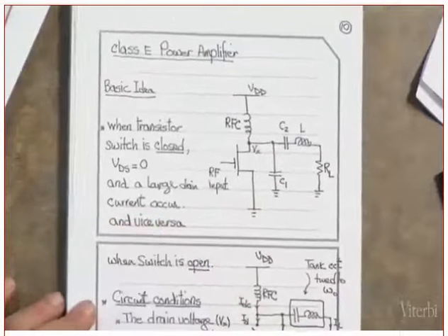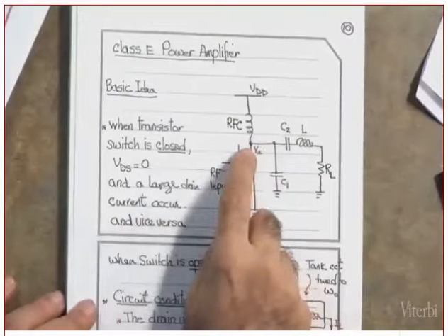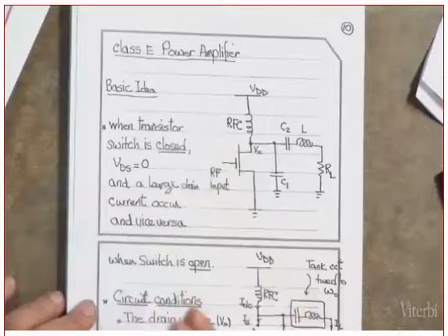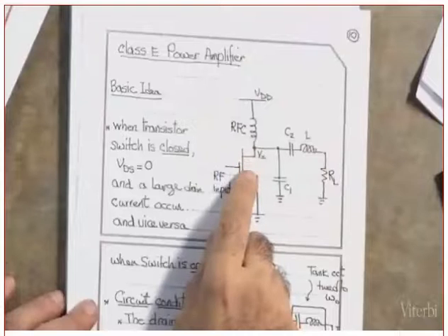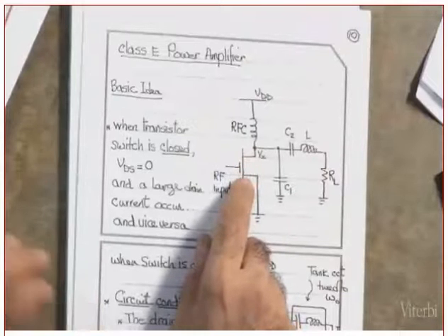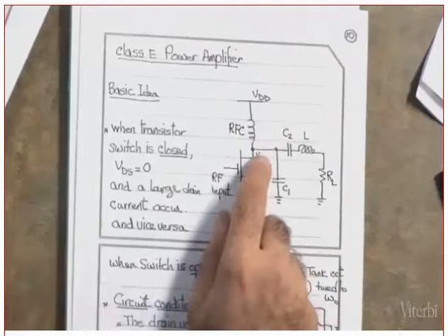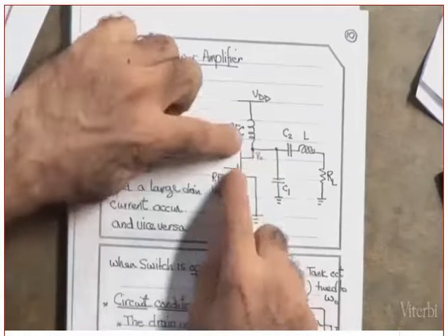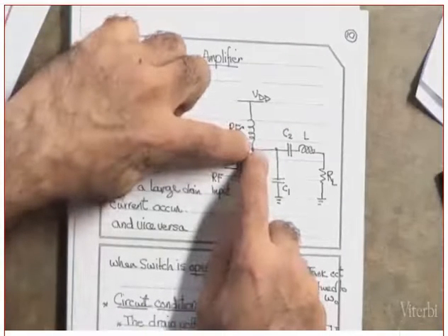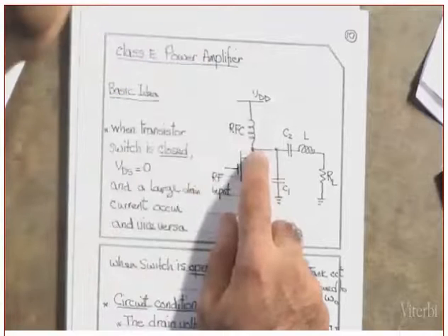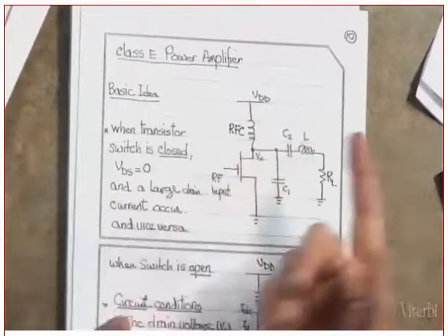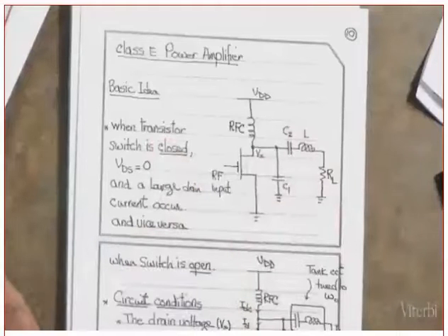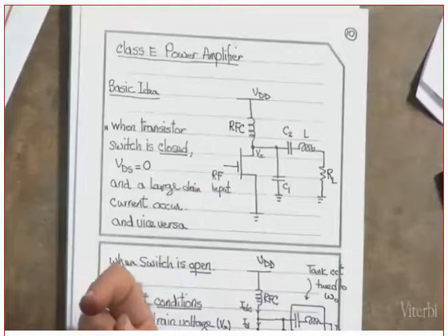Is that better or worse, when you have 3.6 VDD here? But you need to look at it from a different point of view. If you are going to use the new technology, new sizes for your transistors, those small sizes cannot handle the 3.6 voltage in here. Actually, even the 2 VDD is relatively high. Did you understand what I just said or not? There might be a breakdown in the transistor itself. Clear? Okay, good.